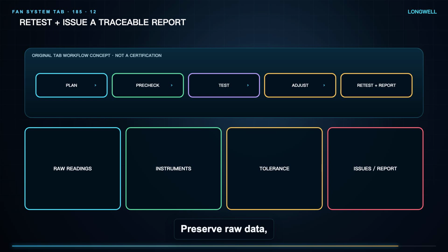Preserve raw data, instrument and calibration details, locations, conditions, corrections, uncertainty, calculations, initial and final values, percent of design, pass status, deficiencies, and unresolved issues. Restore ports, panels, filters, guards, labels, and settings. Commissioned performance is repeatable evidence across defined modes, not one airflow screenshot.